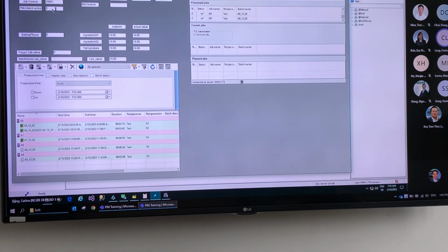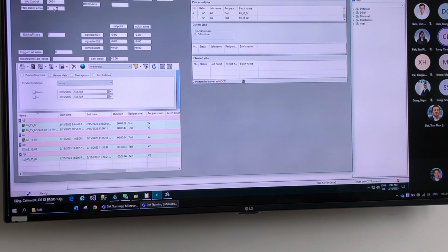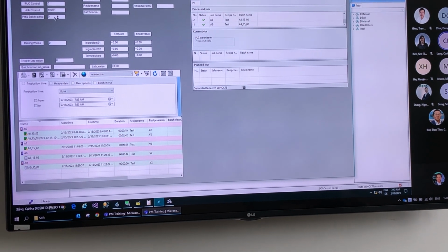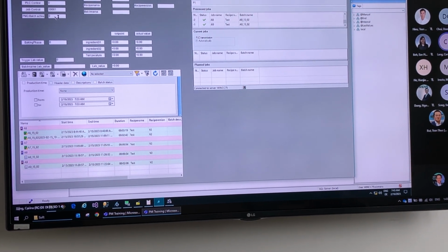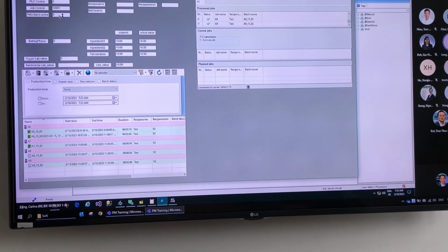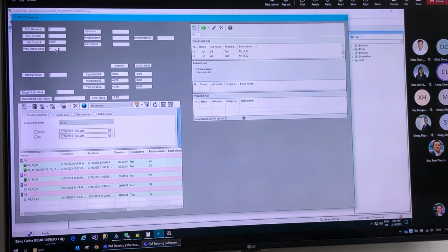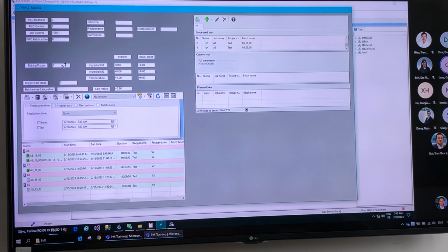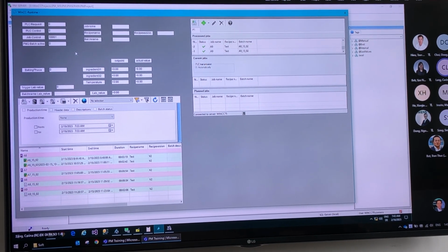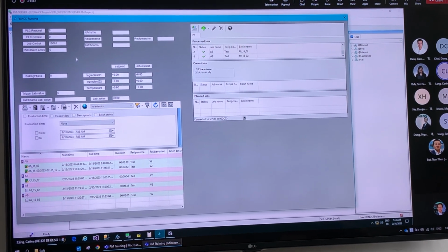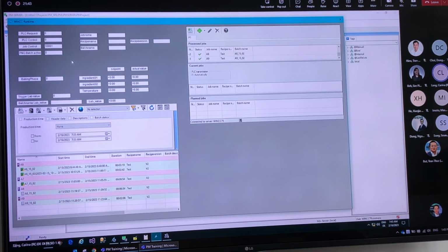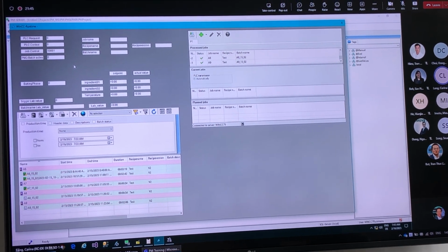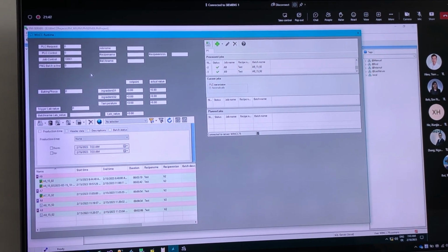For example, we can record all the alarms, all the snapshots, then all the phases and so on. So while the batch is running, we record all of the data, and after we close the batch, we had the setting that the batch was automatically released. So it changes from a processed state to the released state.